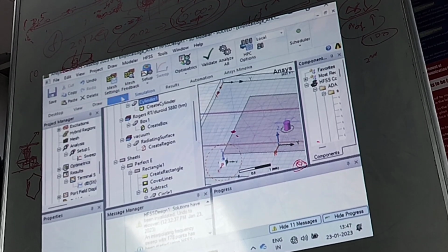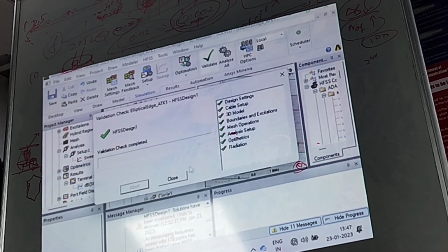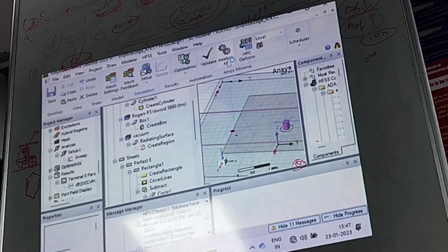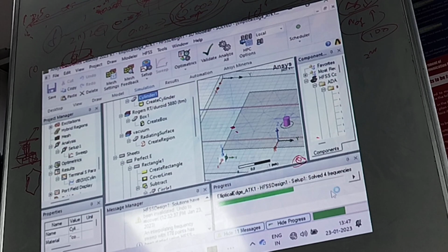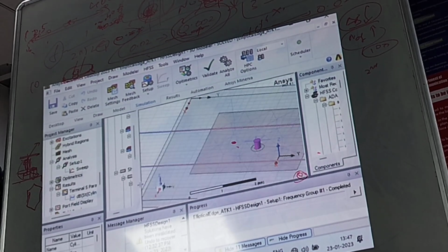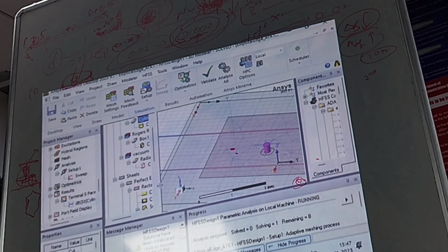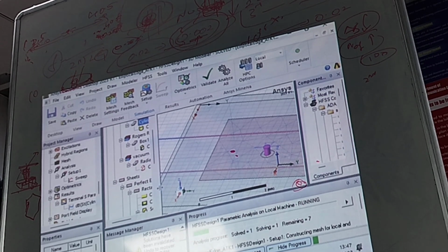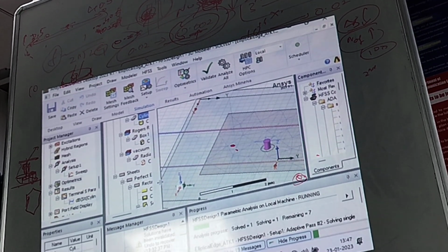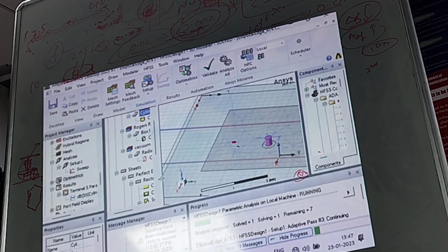So once we click OK and go for simulation, we can validate and just click on analyze all. Now here almost 9 simulations will be running at a time. It is kind of changing that particular parameter each and every time. We are just running it in a single stretch. That's it. So let this get simulated. You will get an idea after seeing that reflection coefficient how this position makes an impact